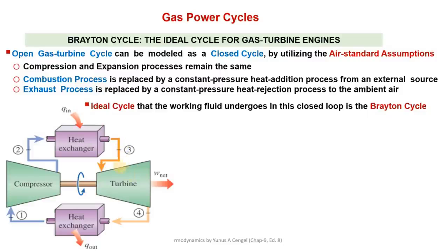So for this reason, the blades which are used in case of gas turbines need to be cooled with air that flows out of some small openings and creates a protective film between the exhaust gases and the blades. Without cooling, the blade material will quickly wear out, right? So in the case of gas turbines, we need the cooling of the blades because the temperatures attained here are very high, right?